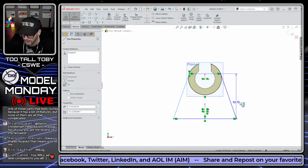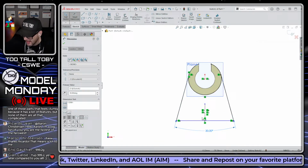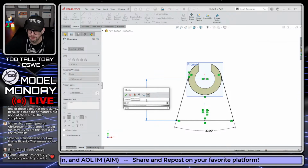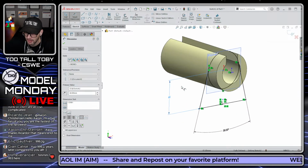Make sure I'm not overlooking anything. All right. So now this guy is going to have an angle of 30, and this is going to be a distance from the center of the arc down to this location with a value of 80 minus 20. So just so we come down to the top of that foot plate.